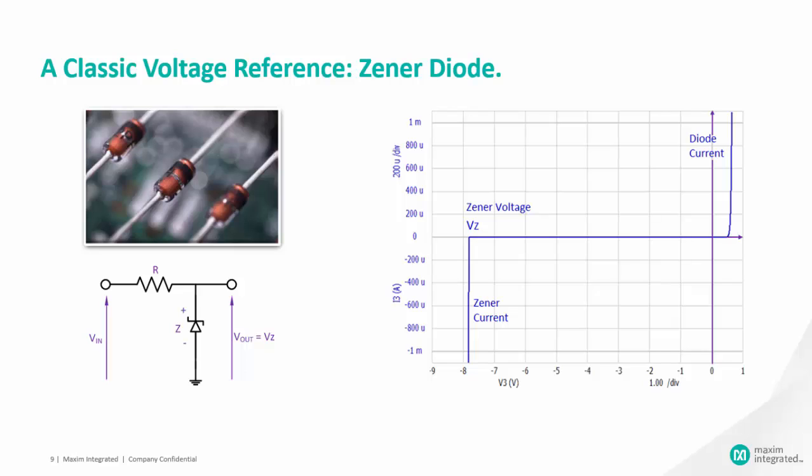The breakdown in heavily doped silicon junctions is due to the Zener effect of quantum tunneling of electrons through the junction and yields low voltages in the sub 10 volt range. Lightly doped silicon junctions break down at higher reverse voltages. Under a high electric field, the free electrons are accelerated and hit more electrons in their path, energizing them in turn. This creates a chain reaction or avalanche mode.